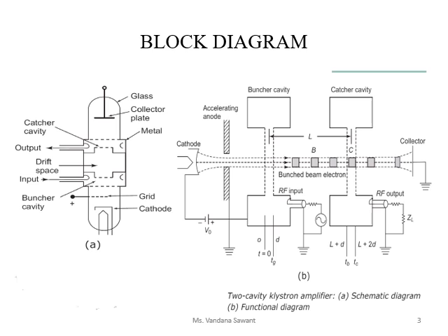Because of that, whatever field is inside the cavity will not affect the distance L. The field is confined to the cavity, and this length L between the two cavities is the field free space, also called the drift space. Because this space is field free, no change takes place in the path of the electrons, as there is no field. Similarly, as L is quite large, by the time the electron reaches the catcher cavity from the buncher cavity, the phase of the RF signal has changed.